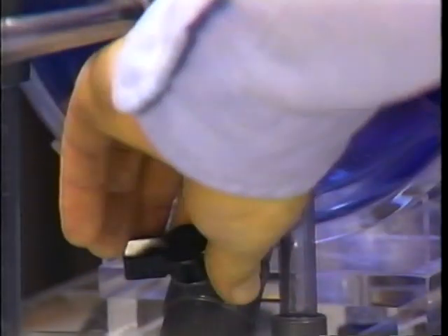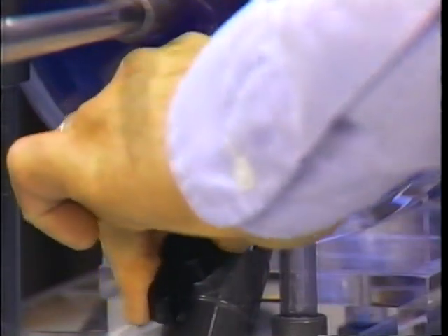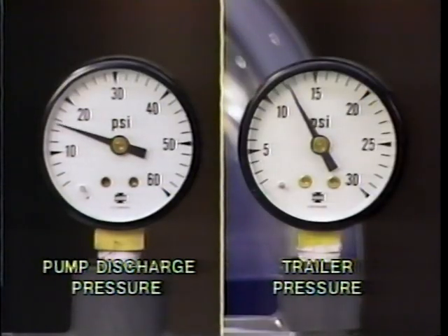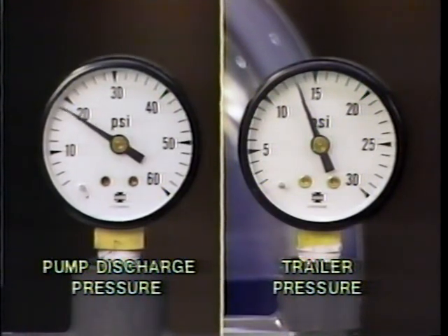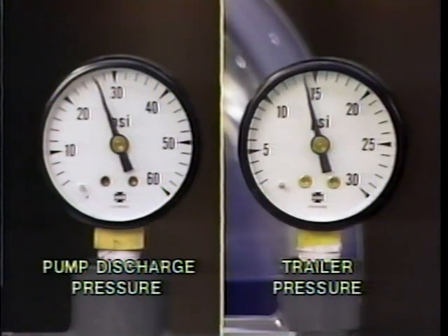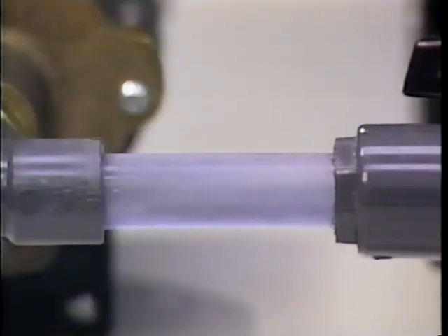By using the pressure building coil and raising the pressure in the trailer just a few pounds, the bubbles in the pump suction line recondense to liquid form and a good prime is restored. Pump discharge pressure has gone up and there is good solid liquid going to the pump, which will provide adequate flow to the customer tank.